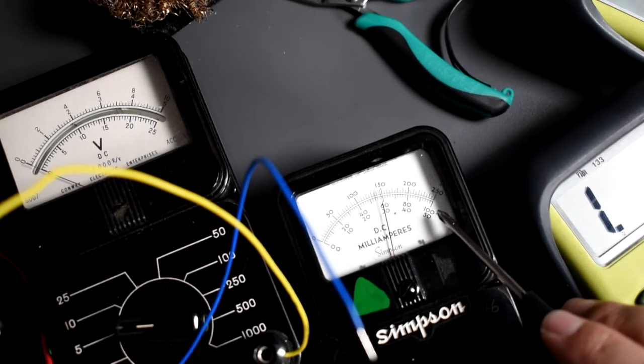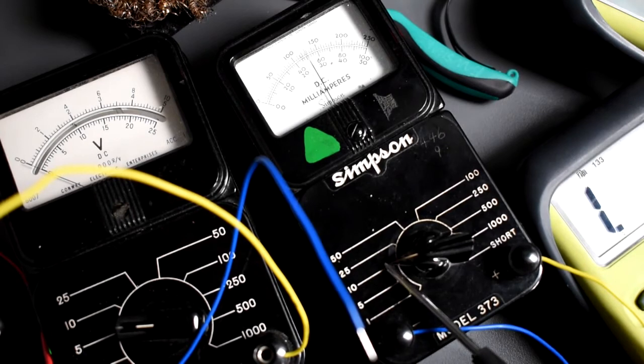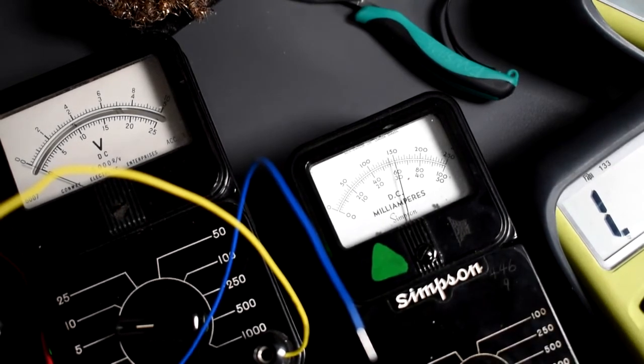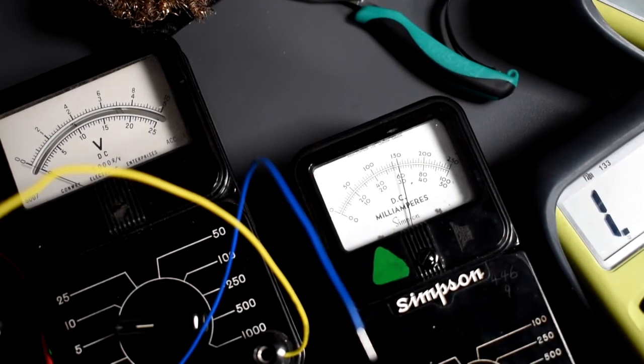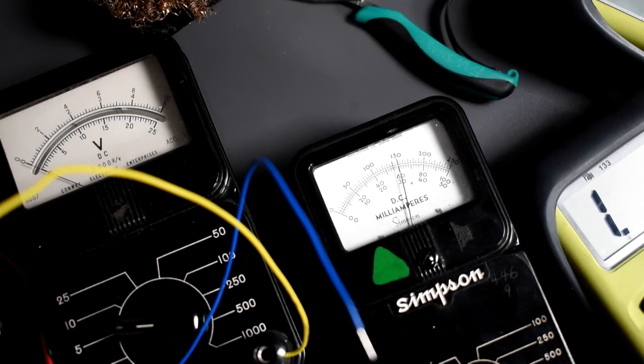Okay. So what you do is you take this range, which is 10 milliamps, 10, and divide it into 100. So 10 divided into 100 is going to be 0.1. So whatever shows here on the scale, you're going to multiply the reading by 0.1. Now, what we have here, we have some bad connections. This is an old meter here. So 60 times 0.1 is going to be 6 milliamps, because these are milliamps. So 6 times 10 to the negative 3. So 6 1,000ths of an amp. That's how you read this.